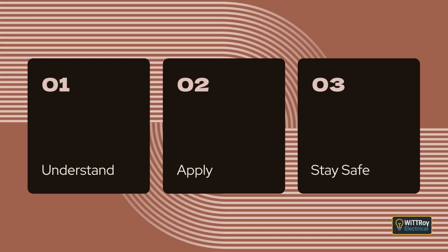An exception is allowed when the switchboard is enclosed with tight-fitting doors or placed in an enclosure that protects it from splashing or steam. If a switchboard is placed inside a cupboard or enclosure, the cupboard must be designed properly. The switchboard must be in its own section of the cupboard. It must be positioned at the front so a person can operate or maintain it without reaching awkwardly. The cupboard door must not push objects into the switchboard when closed. There must also be no objects in front of the switchboard that make access difficult.